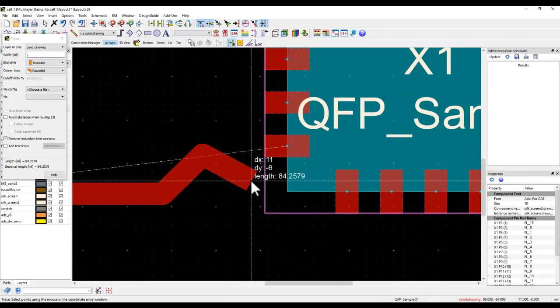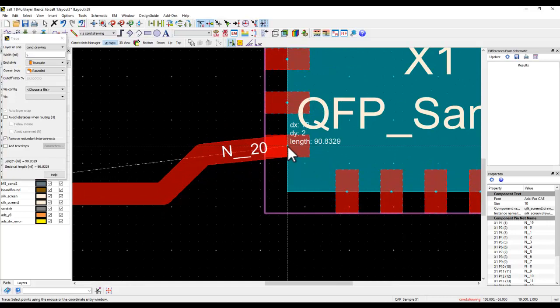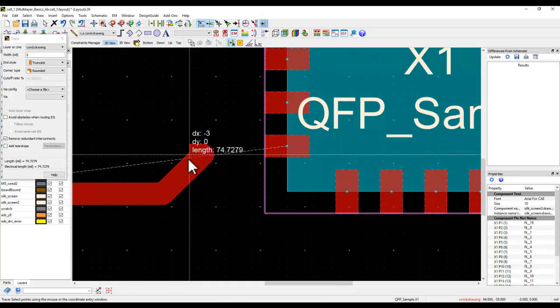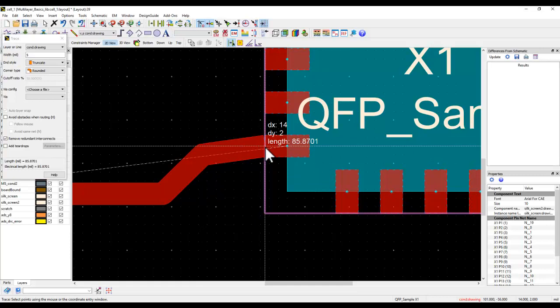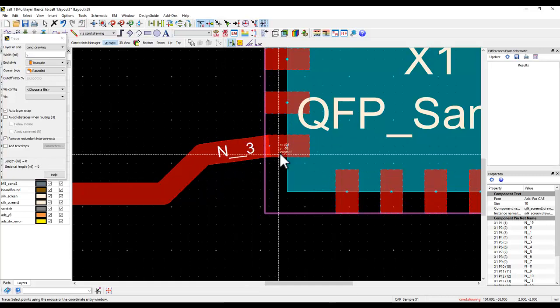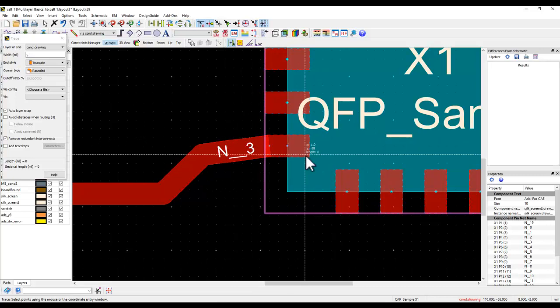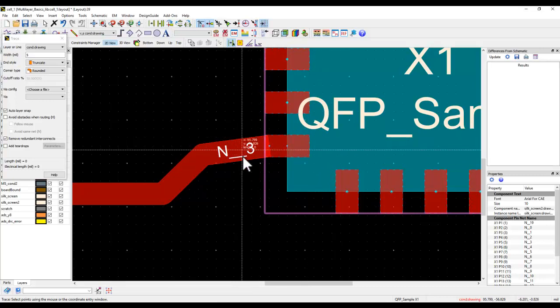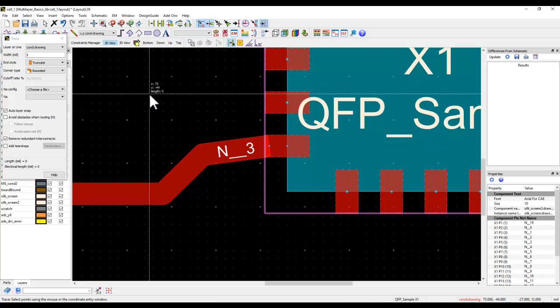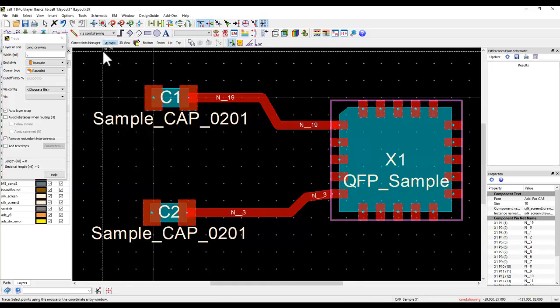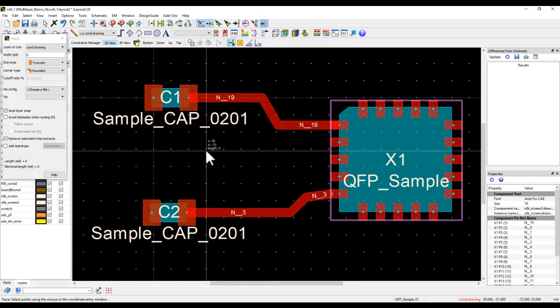Now again, another thing, to connect, you don't need to really touch this component here, because if you are only touching this particular piece, then also the connectivity is done. Remember, because this entire pad was defined as a connection pin, so as long as you touch that component, that should be fine, and you will pass LVS or DRC checks, there's no problem.